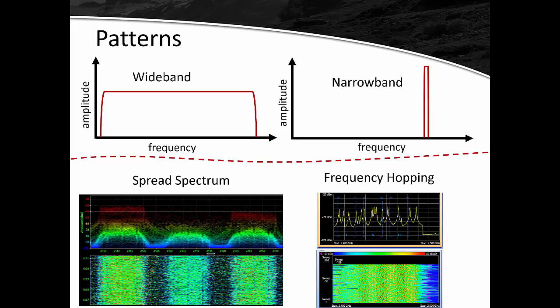Of course, it has to communicate, and so it's simply the fact that if you're in 2.4 gigahertz, which is where Bluetooth is, and you're running 1, 6, and 11, and you've saturated your environment with it, Bluetooth is going to have to interfere some.